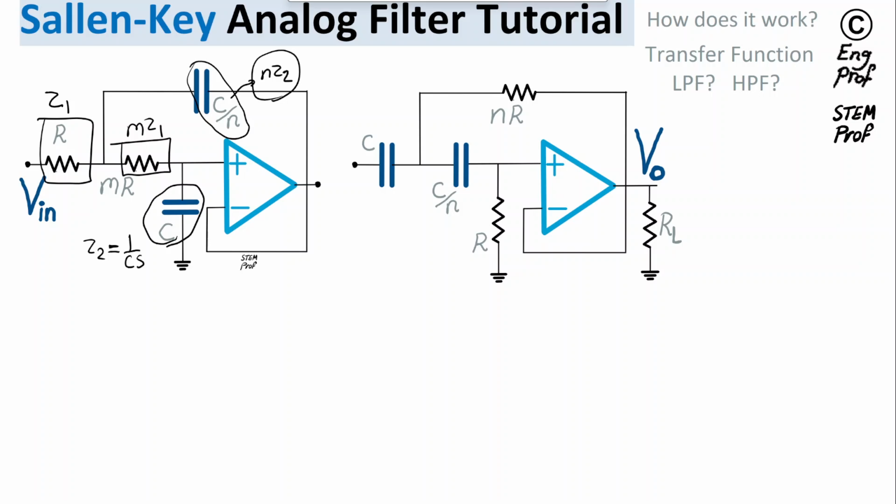So what we can do is let's make the assumption that the op-amp is properly biased. Let's say plus minus 5 or plus minus 10 volt supplies connected, and also you can see that in this circuit the negative feedback is properly there. From the output we are having a connection back to over here, back to the negative input terminal of the op-amp, which indicates the negative feedback in this system. Effectively, this op-amp is acting as a buffer or unity gain amplifier. So let's see how this circuit is working.